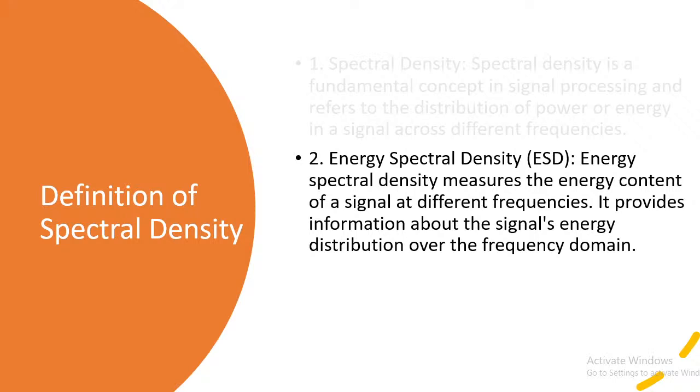That is a graphical representation of it, and it gives us information about the signal's energy distribution over the frequency domain. It is important to remember that when we say spectral density, we are dealing with the frequency domain part of the signal, not the time domain, because the graph is between frequency and energy.